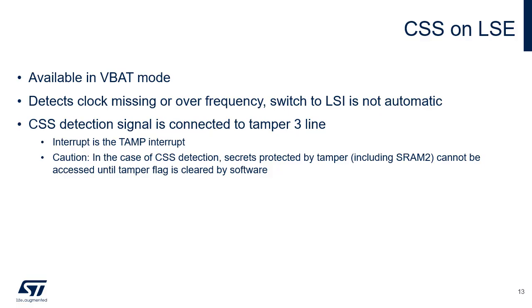The CSS on LSE failure is connected to a tamper event. In the case of a failure, the application can switch the RTC clock to the LSI. This is not automatic. The tamper flag must be cleared prior to accessing the secrets protected by this tamper.